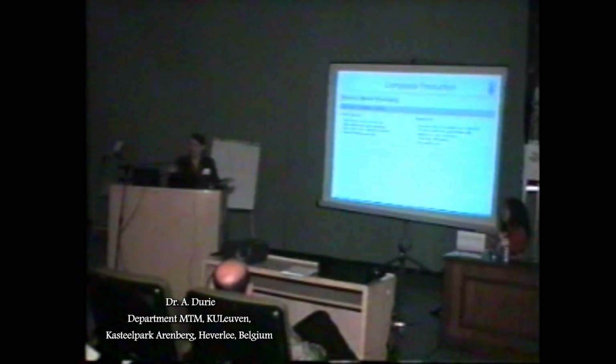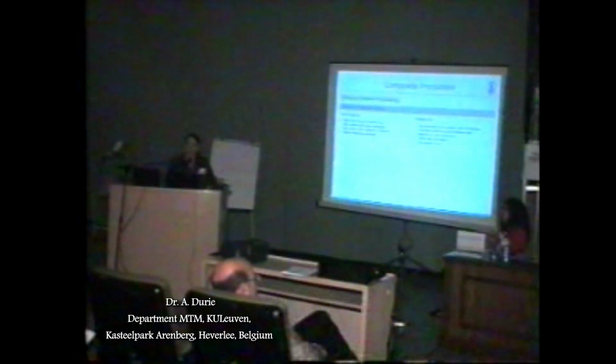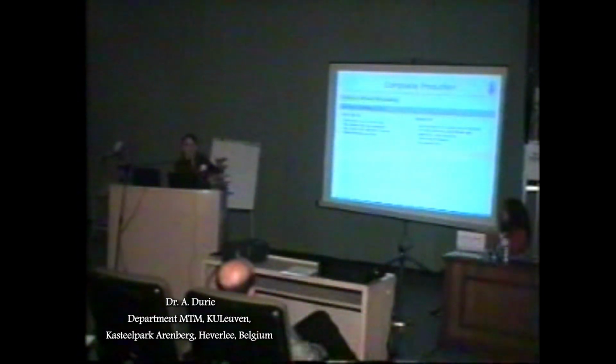But anything above that, we really needed a new method to look at how to make them in a reasonable way. The other problem with doing hand layout is that we can't control the amount of stretch that we get. We can't control the height very well. And also it's very difficult to control the fibre orientation in each direction between the panel layers.